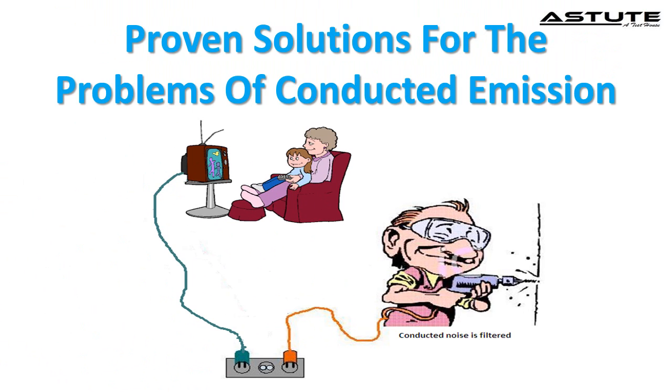There are different solutions available to remove or minimize the emission of conducted noise from the device. The methods are as follows. Use line filters or total EMI filter or power line filter. Minimize the dV by dt. Reduce the parasitic capacitance. Use filtering to reduce the common mode current on the cable. Use grounding to return the common mode current.